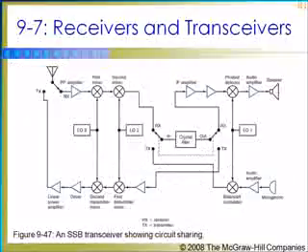In this slide, this figure is a general block diagram of a high-frequency transceiver capable of CW and SSB operation. So, in transmission mode, the crystal filter provides sideband selection after the balanced modulator. The filter provides selectivity for the IF section of the receiver. Tuned circuits may be shared. It can also tune input for the receiver and tune output for the transmitter. In most newer circuit designs, both the transmitter and receiver share a frequency synthesizer.